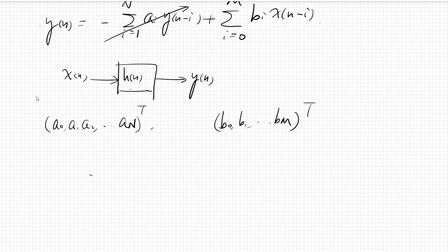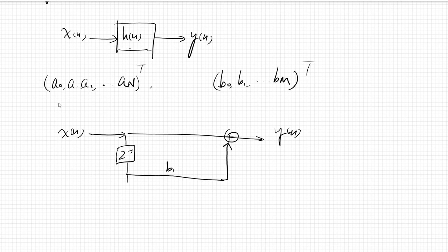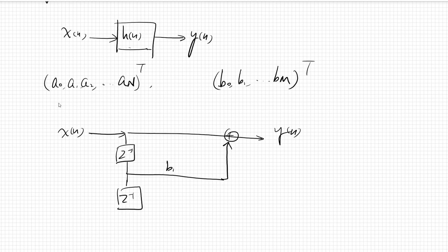So look at this channel. It's a delayed version of x all the way to y[n]. So we have a delayed one, adding here, and weighted by b1 here. And I have another delayed one. Let's just draw 2 of those. And adding here with weight of b2. So this point is x[n minus 1]. So that is the delay. I have the tau exactly equal to 1 single period, T sub s. And then I have that.